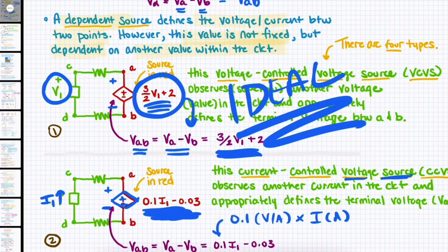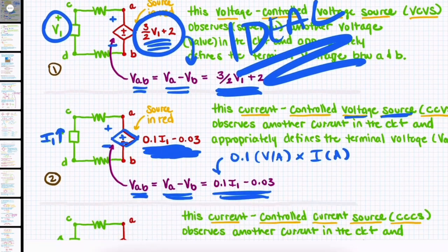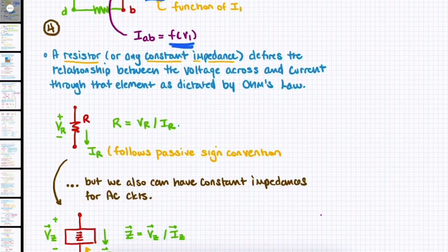There's assumed either no internal resistance for the voltage source or infinite parallel internal resistance for the current source. We assume that it's completely linear, etc. So, generally these are idealized representations of real sources. You do not find real sources that operate in this way over large operating ranges, for the most part.